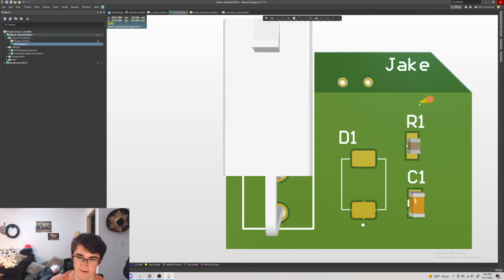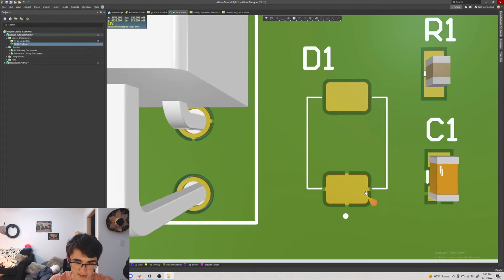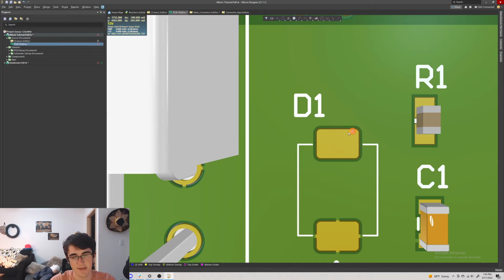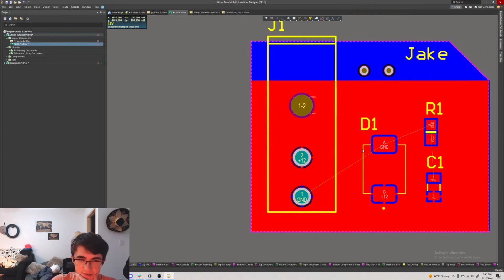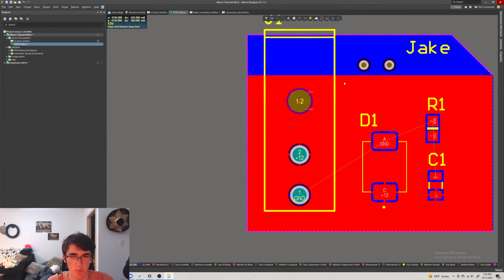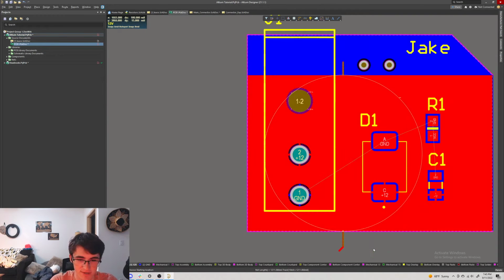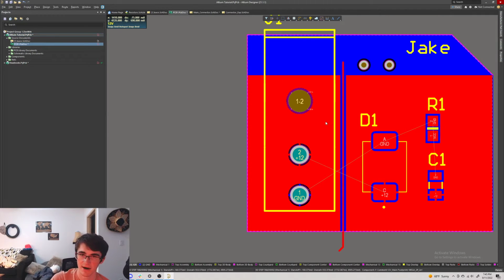But in Altium, I hide it with a different color like this. And you can see, since this is conductive and all on the same part, it'll go from 12 volts here, to here, and then to C1. This can get a little tricky, because you can have a trace that goes like this and completely cuts your plane off. This is what we would call an island.